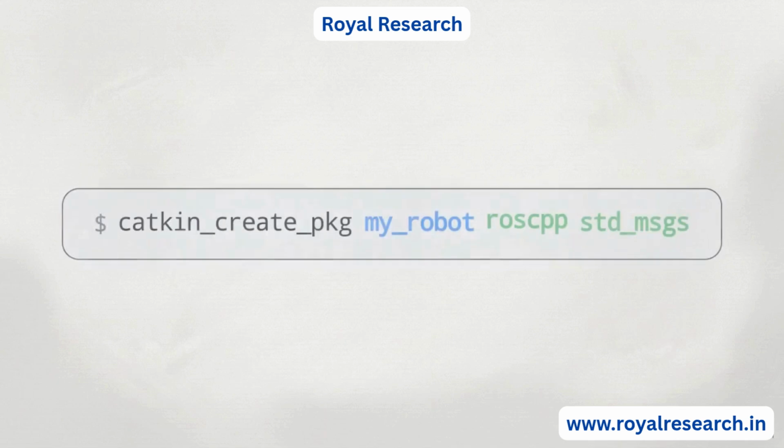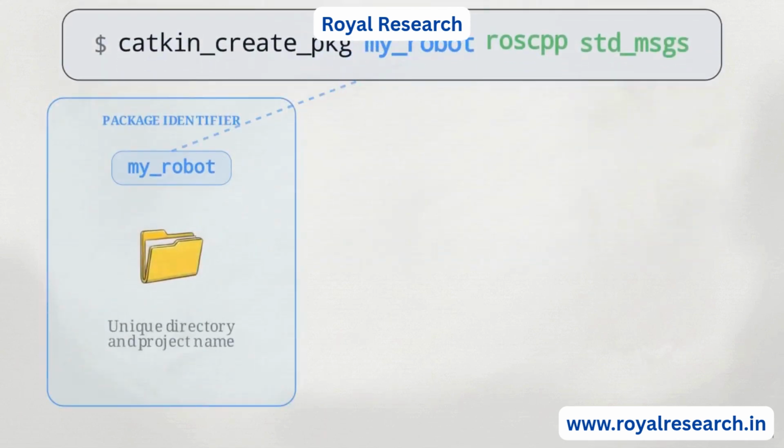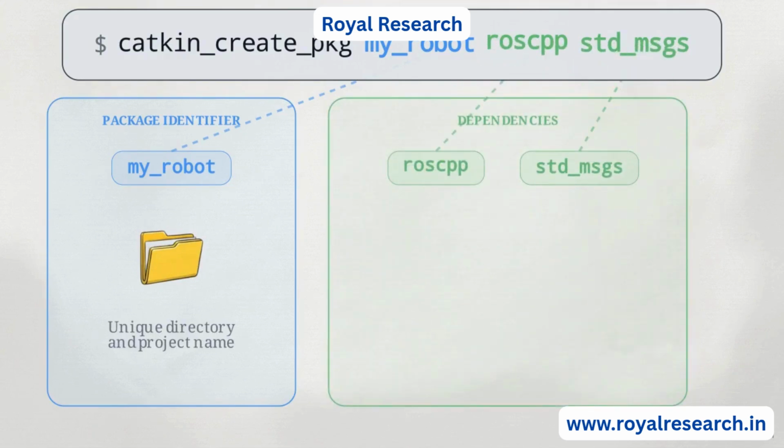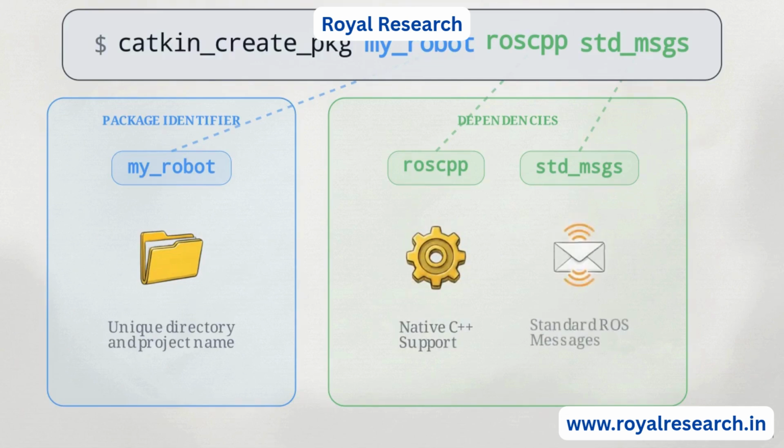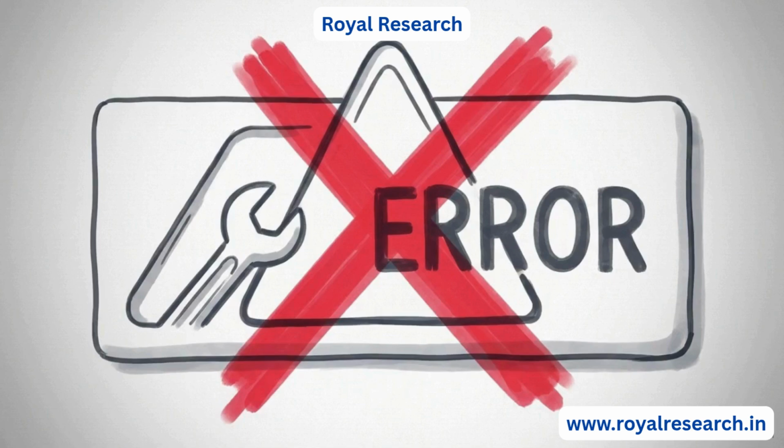Breaking down that input string, myRobot serves as the designated identifier for your new package. The subsequent terms, roscpp and std_msgs, define the specific capabilities the package needs. They grant your code native C++ support and the ability to process standard ROS messages. By explicitly defining these required dependencies right now during the creation phase, you ensure the package links correctly to the broader ROS ecosystem and avoid complex compilation failures down the road.